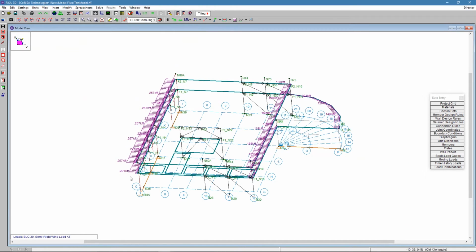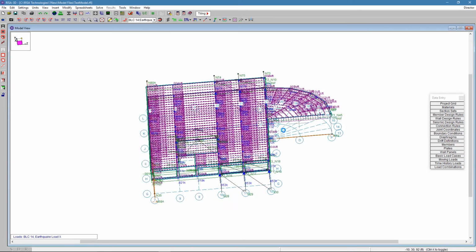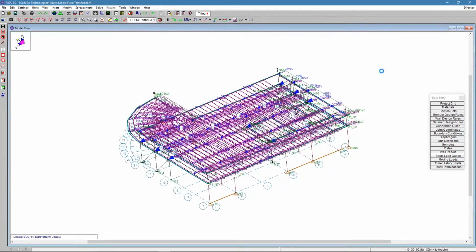And so you've got your wind loads applied, and now you're going to worry about your seismic loads. For seismic loads, we can just look at the ELX, for example, and that is a little different. So seismic is based on, if you think about it, wind blows onto the side of your building. So we smeared it along the edge. Now for seismic, what we're doing is we're doing it based on the weight. So instead of just smearing it in one location, we take it and distribute it based on the weight of the entire slab, or the entire, this is metal deck. So, but anything that you have for the semi-rigid, it's being applied along that entire thing. So this participates along the entire actual diaphragm.